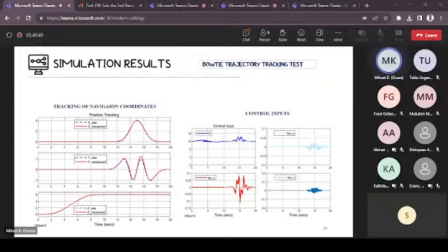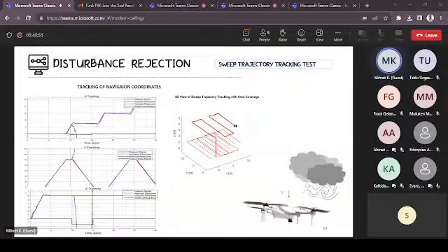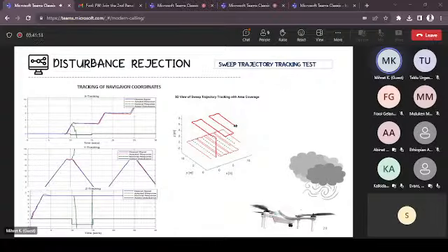Another case has been performed to test the disturbance rejection capacity. This test has been performed on the switch trajectory, which is a typical type of area coverage trajectory. A disturbed environment with counteracting roll and pitch movement and a counteracting longitudinal disturbance has been applied. And it can be seen from the plot that the fixed gains of the nominal controller fail to ensure stabilization and drive the system to instability, while the adaptive augmentation has maintained tracking and has maintained stability of the dynamic states.